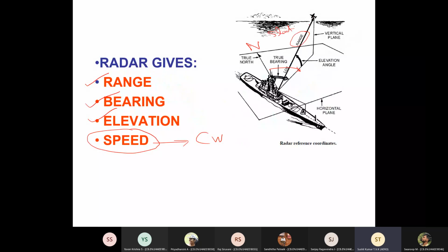That is from aircraft to the radar, and it's not the distance. Okay, actual distance, geographical distance. You'll have to do some calculation and then try to get it. Otherwise, also it's okay. It's not going to create much of a problem for a search radar. But definitely in case of missile tracking radar, we'll have to take care of this vertical angle, the elevation angle also.